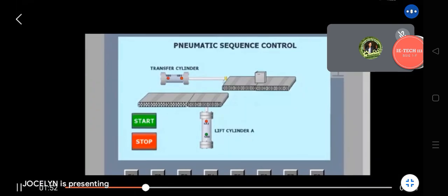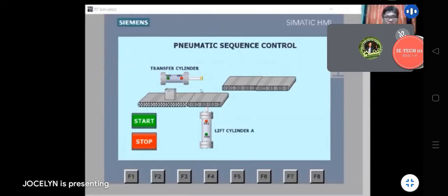It is fully retracted, especially if we have a throttle at a certain percentage, guys. It's not 100%. If we slow down the extraction or retraction to 20%, 50%, or 45%, the retraction and extraction will have the same speed. Unless we use the one-way flow control check valve with 100% output, so it returns immediately.